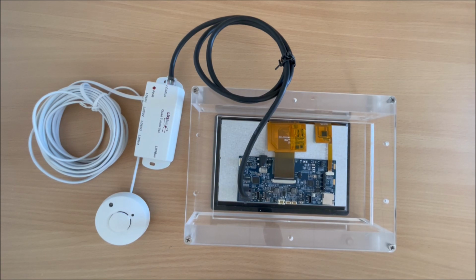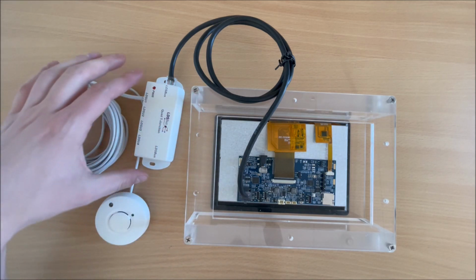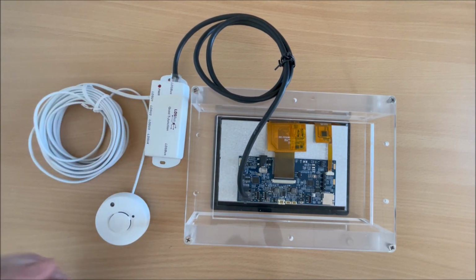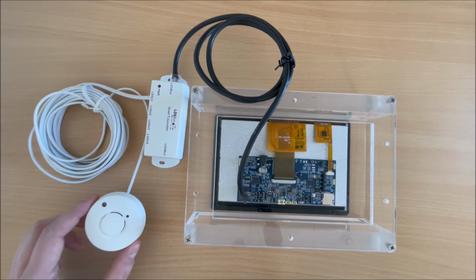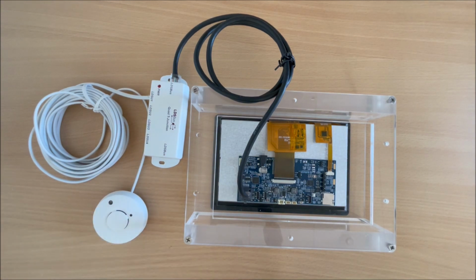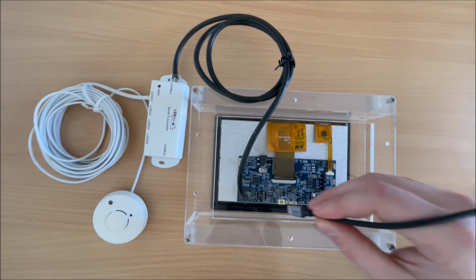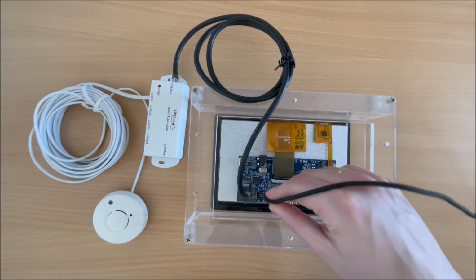Finally, here we can see our hardware setup for our IDM2040 and LDSBus demonstration. Firstly, we have the IDM2040 display module. Connected to this via the RJ45 port and a Cat5 cable is the HVT junction. Connected to the HVT junction is an LDSBus CO2 sensor. To power the demo, we want to use a power delivery capable USB charger and connect this to the CN12 connection on the back of the display, ensuring that the W1 jumper is left unpopulated.